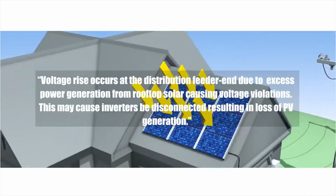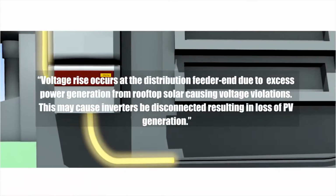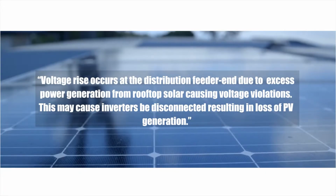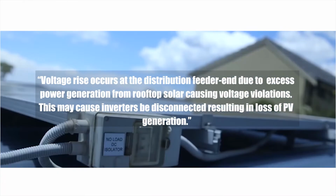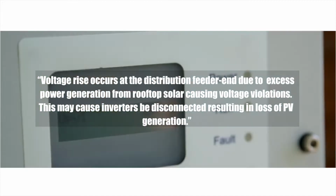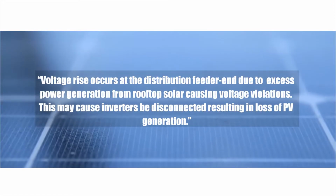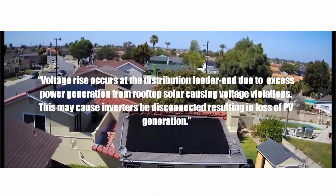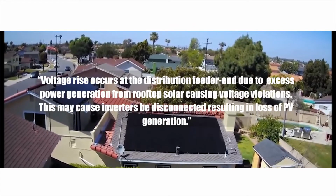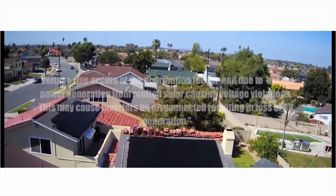There is an existing issue of hosting capacity limitation in the LV distribution feeders in Sri Lanka. If the PV generation is greater than the local demand at the point of common coupling, the excess power from PV inverters may produce reverse power flow in the feeder that would create voltage rise. Due to that, further addition of grid-tie rooftop solar is limited by the authorities. Therefore, this is a barrier to the renewable goals of the country.